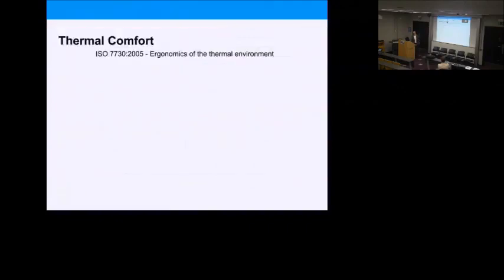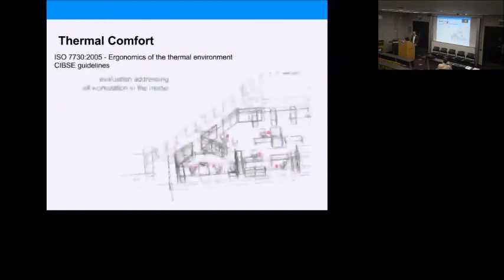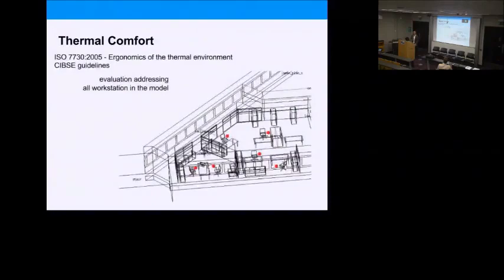What you're going to get out of that, let's say for thermal comfort, you use the ISO standard with 5 different criteria. It's going to run a CFD model for each one of the rooms, get each one of the positions and say whether this complies or not with the standard in that particular criterion. Which in previous times would require coming to a consultant. The consultant makes the model, goes back to the office, writes the report for a specific day, brings back the report. Oh, I would like to see it for the next day. Another cycle, while here you can just change the dates, and this pre-configured model will do the work for you. And again, for every chair of the area that you're addressing.